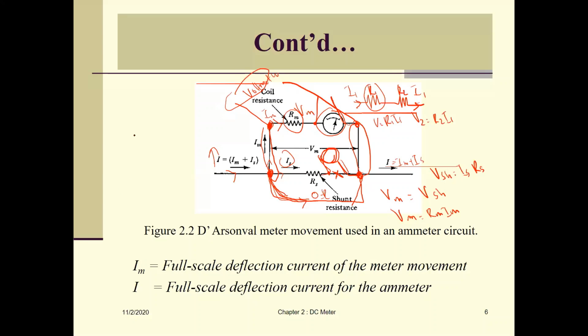For example, with another circuit here, this is our supply and this is our circuit. The current flowing here we call I1, so it will be the same as the current here, I1. This one we call R1, R2, for example. But the voltage here will be different. The voltage here will be R1 times I1. This one is for calculating R2 times I1, for example to calculate V2 here. That's why the voltage will be different.